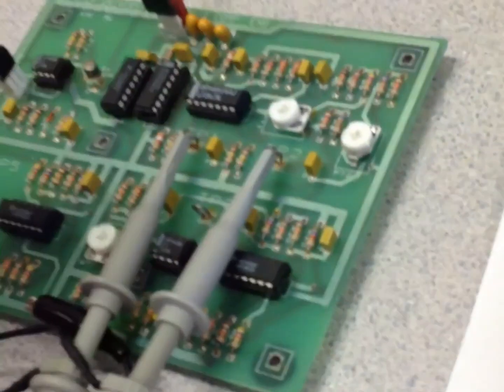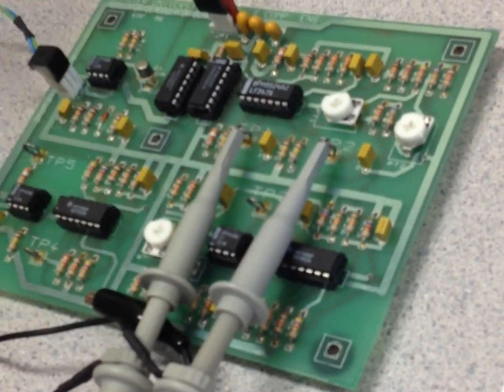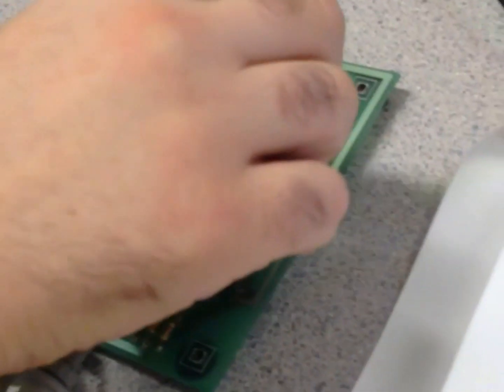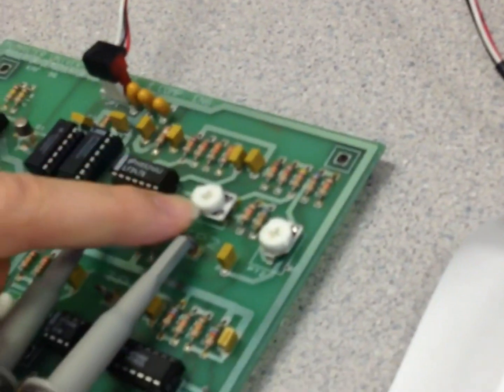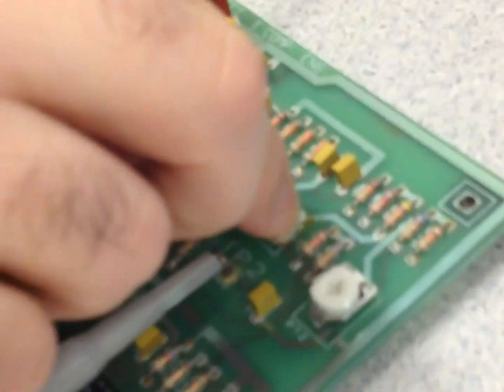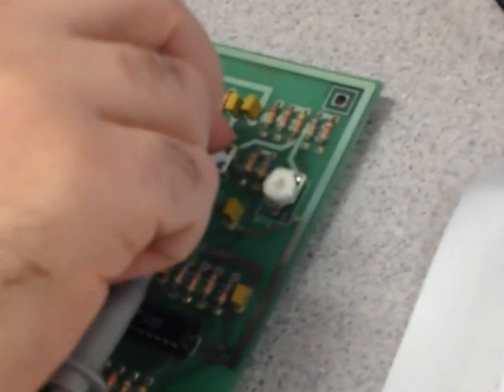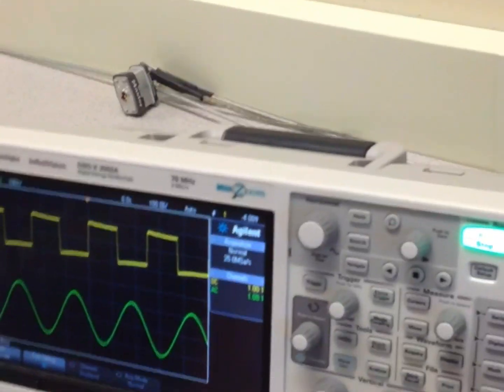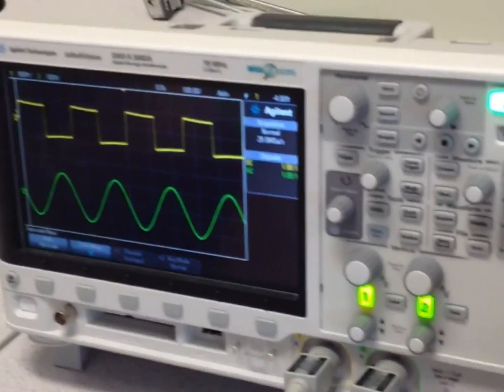Okay, so now we have test point 1 and test point 2. We have our square wave, which is 4 kilohertz. We are ready now with our 4 kilohertz sinusoidal message. The level of your message, if you look at PT1, is a potentiometer. Potentiometer 1, as you know, is a variable resistance. It changes the amplitude of your message. So as I change the potentiometer, the amplitude of my message changes.